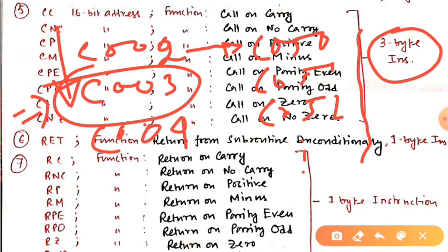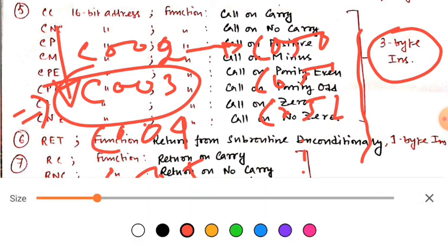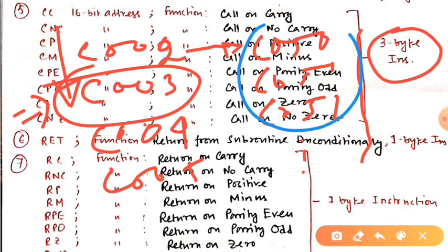So in the memory location C003, then C004, then C005 onwards. That is why, when we use the call instruction to go to the subroutine, this part is actually called the subroutine. All the instructions written in this particular set of memory locations are called the subroutine. So from the main program we have shifted to our subroutine, and we are executing the instructions written in the subroutine. And at the end of this subroutine, suppose this subroutine ends at the memory address C055.